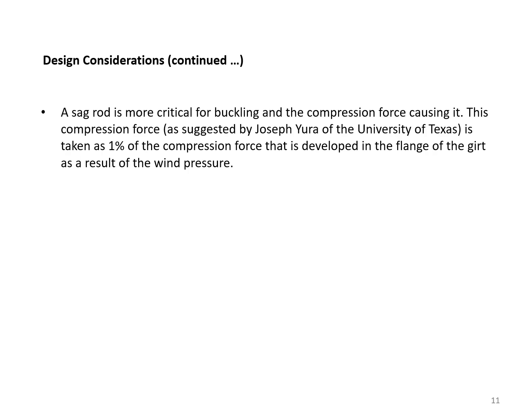Let's continue with design considerations. As we discussed before, we need sag rods. A sag rod is more critical for buckling and the compression force causing it. And you might say, just a few minutes ago, we talked about the tension force in the sag rod. So what are these compression forces?